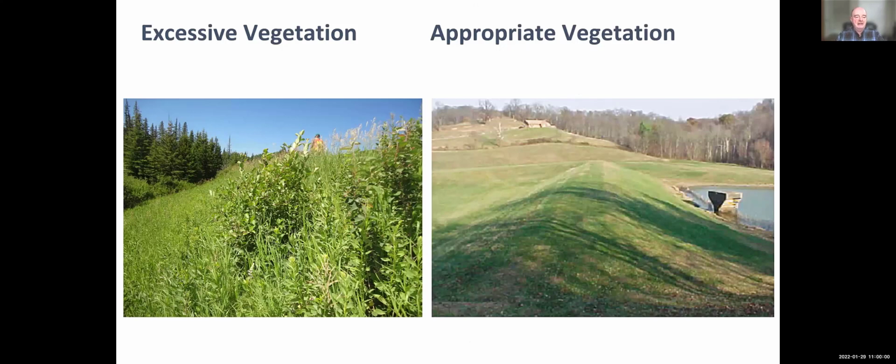Another example: there's a person walking along the crest of the dam. We don't have very large trees on here. Some of these might be too close to the dam over here in the background. But there are those alders again and other vegetation. That's violating that rule of thumb for vegetation being one inch thick, because you can't really see anything on that embankment. It's an area where things grow really well, and once it's this thick, you just can't see what the dam's doing.